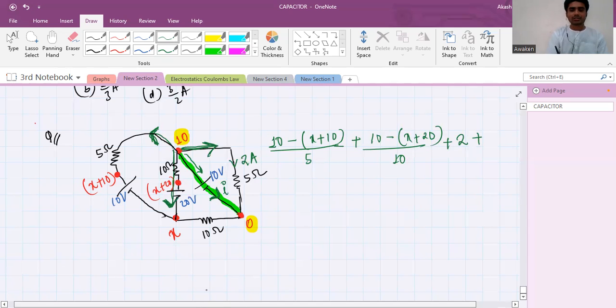So now you see, if I'm assuming that 2 ampere is coming in this fashion, and I is coming in this fashion, what is the total current coming in here? I plus 2, right? Now you see, the current in this branch is a summation of the current through these two green branches. If I assume that current is flowing from both those branches, it is combining in pink, right?